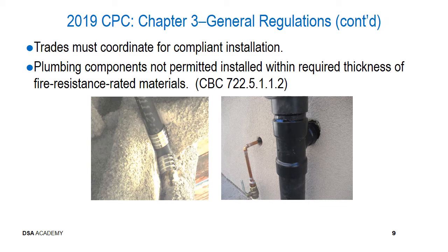Now, I would encourage everyone to not jump to conclusions and instantly presume that the required fireproofing has been compromised by the installation of that upper pipe, because it could certainly be that the plan specifications called for 1.5 inches of sprayed on fireproofing on all of the primary structural members, and for whatever reason, application processes, distractions, whatever the reason, perhaps 2 to 2.5 inches of fire spray was applied, and that the piping that's been installed does not interfere with the required fire protectant spray.